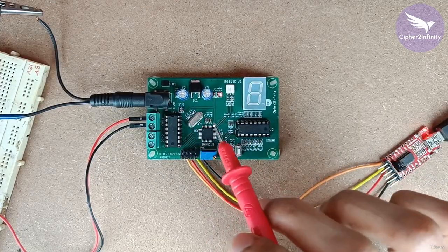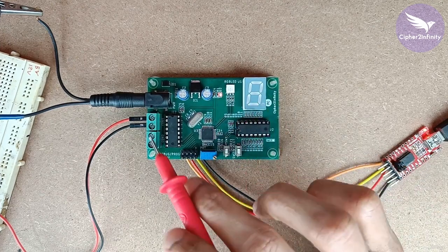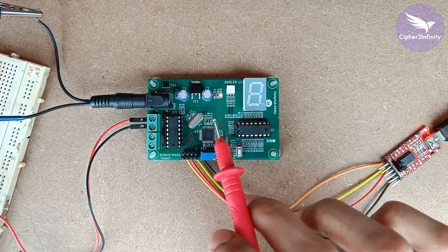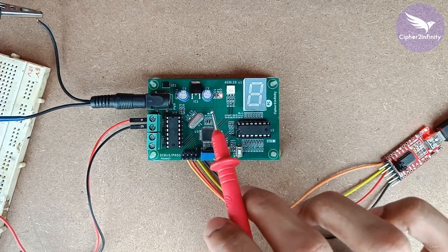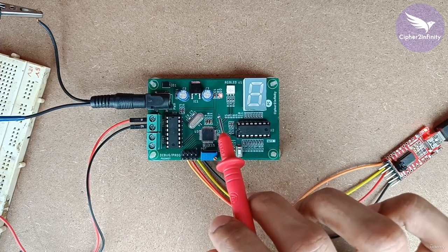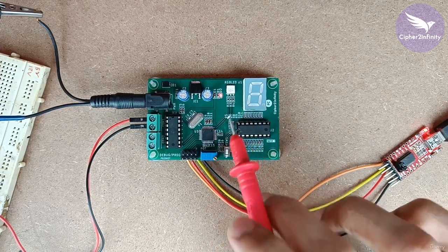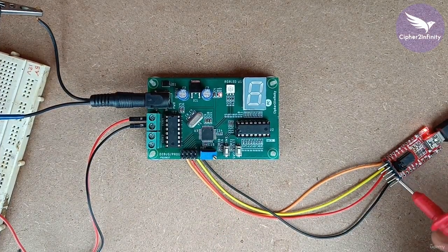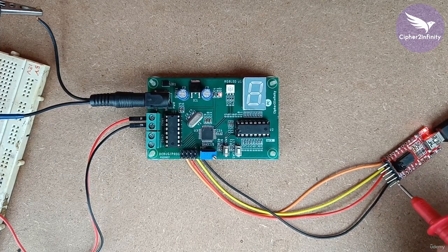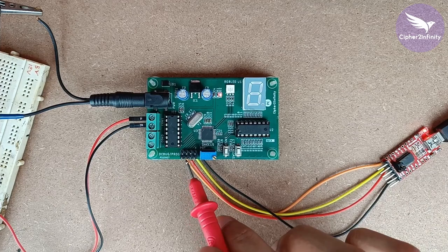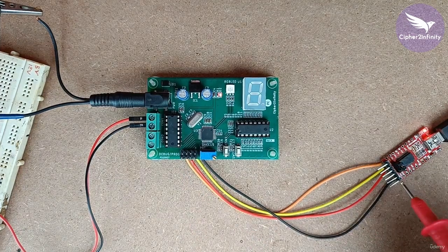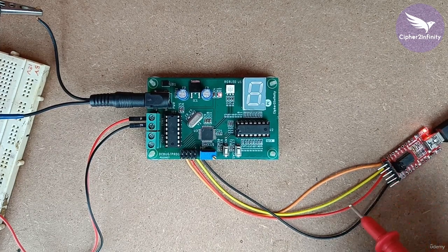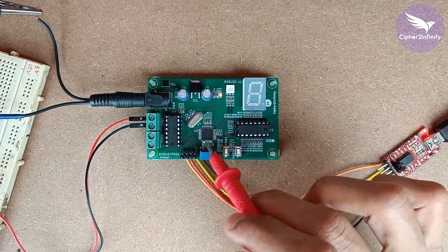As I told you, in this video I'm going to show you the capability of this particular hardware. You can also consider it a small project. We are going to send some characters like ABCD from the terminal on the computer. Those characters will travel through this USB to UART converter, and we will receive them over the RX pin of this controller. The RX pin of the controller is connected to the TX pin of the USB to UART converter, so the converter sends the data over TX and it is received on the controller side over RX.